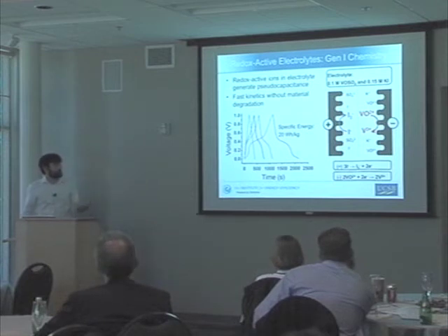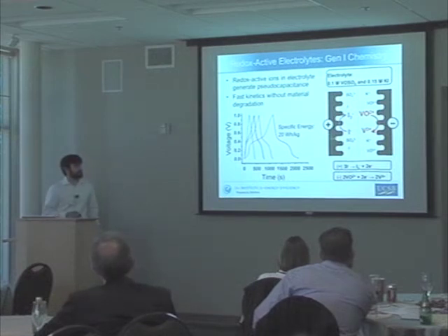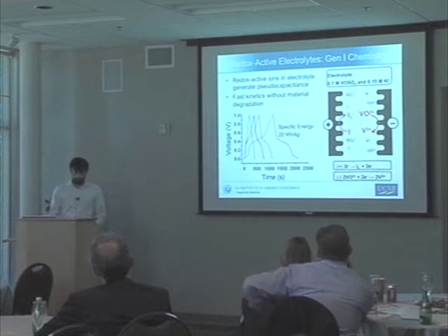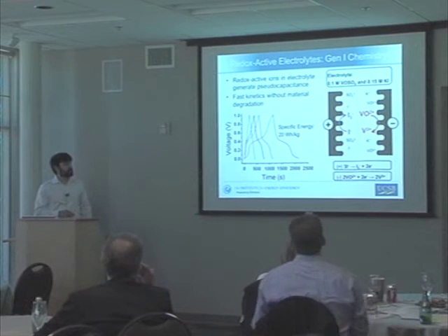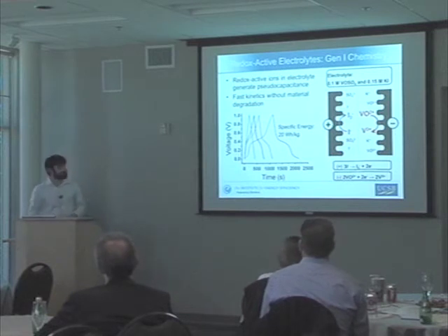This is just the first generation, where we oxidize iodide to triiodide upon charging and reduce vanadium 4+ to vanadium 3+. What you would expect, intuitively, is that as you reduce this and oxidize this, your ions are going to diffuse across the device and discharge. We've engineered ways to overcome that by choosing couples that remain strongly adsorbed to the activated carbon after they undergo reduction or oxidation. So the device can be left at open circuit potential for a long time without internally self-discharging, which is good for a capacitor.